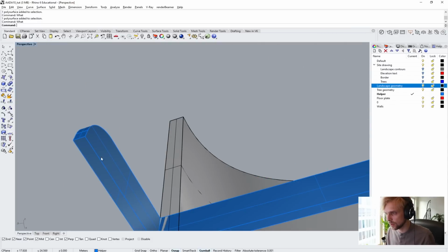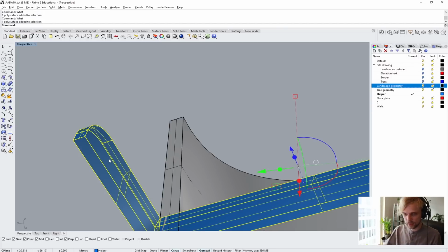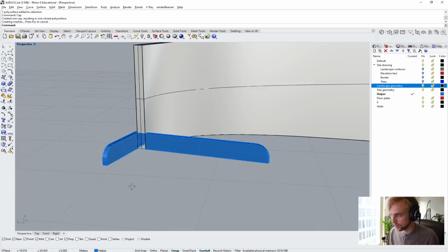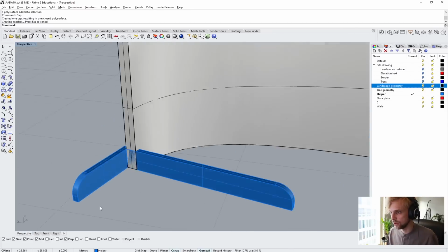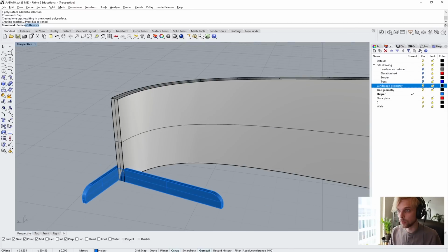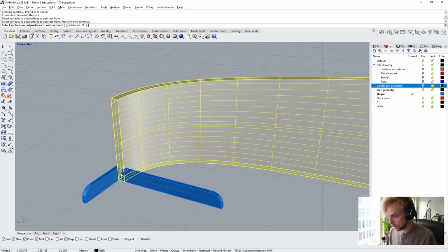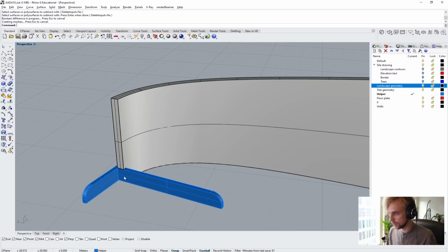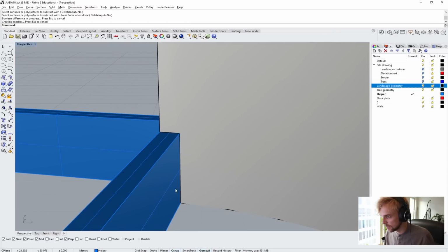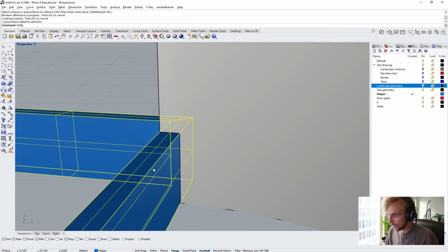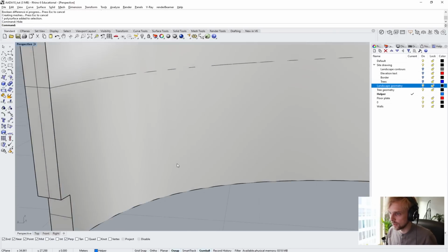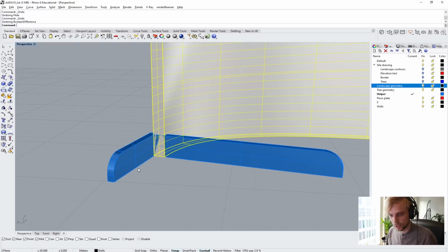So if you have an open polysurface like that, for some reason, then you just select it and type in cap. Because the bottom is flat, it's going to cap nicely, and then you can do your Boolean difference from here, enter with this, enter, perfect. So now you can see that it hugs the retaining wall quite nicely, right?